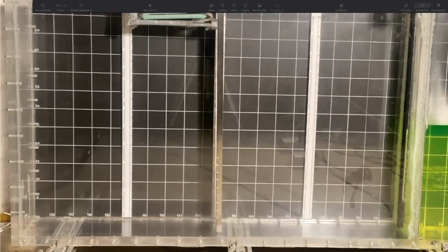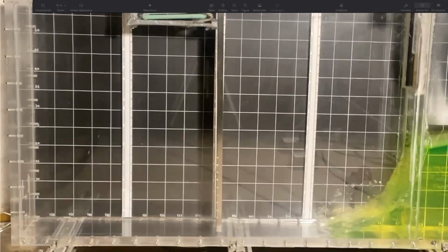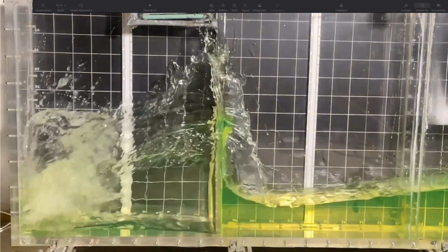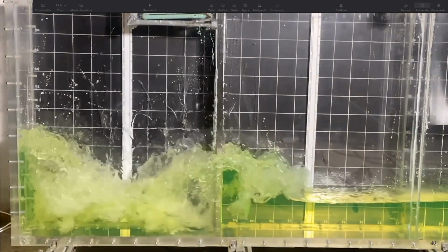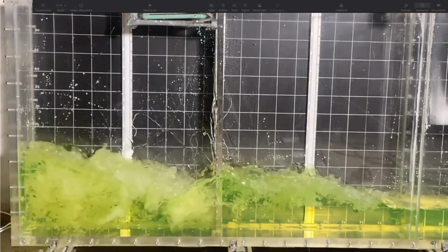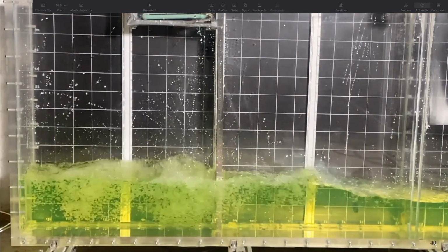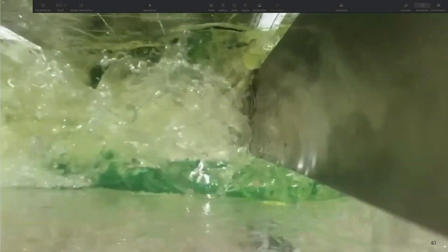Now the pressure has been measured, you can see the cables here, using 3 sensors. These sensors are placed at the same height, so that the hydrostatic component of the pressure is the same for all of them, but at different transversal positions. This allows us to capture the effects on the pressure field of the three-dimensional nature of the flow. Later, we will see if the SPH solver is capable of reproducing these effects or not.